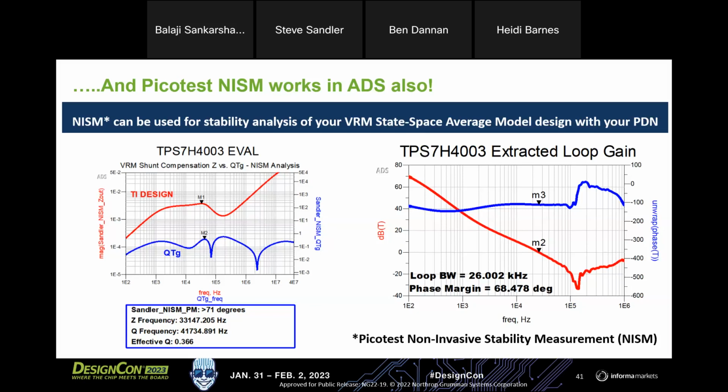And we can generate loads for ASIC using CPM models and attach this VRM model to our PDN, and now have an end-to-end model for our PDN to use for design sign-off in the time domain, which is what we do. And so with harmonic balance, we're able to do that much faster, especially with the density and size of these power integrity and PDN models today, right?